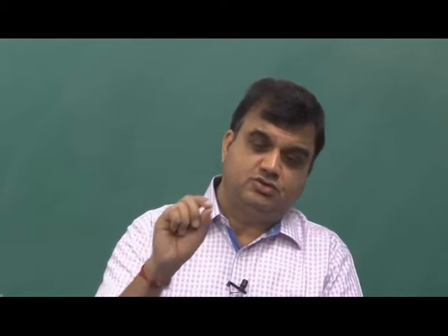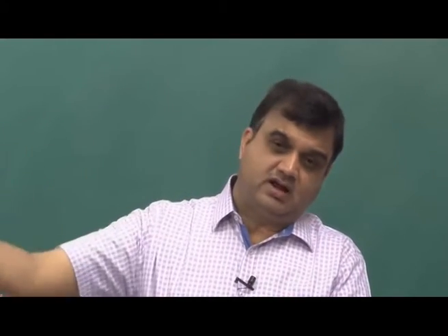So, I will not now focus our efforts on understanding how to estimate LW, because we have already done several examples, and that I am certain would give you a fair idea. And once LW is known, how to estimate LP at a far distance is something we have also covered in our earlier lectures. So, now as I said earlier, we will focus our efforts on how to reduce the overall LP, the sound pressure level, at the point of interest.